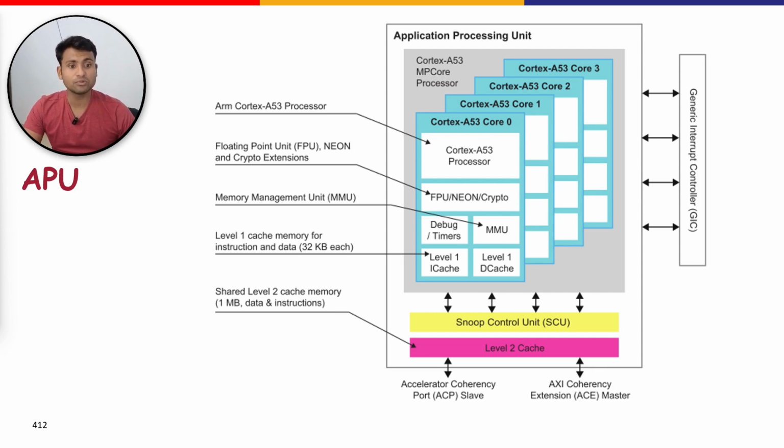And finally, the APU uses an external general interrupt controller known as GIC to support system interrupts. This GIC is the ARM CoreLink GIC-400 IP, which is based on the GICv2 specification. It's just a little finer detail. Primarily, the GIC provides the APU with registers that manage interrupt sources, behavior, and routing between the processors. This is like an overview of the APU architecture. We'll go into more depth of how to program the APU in a later video.